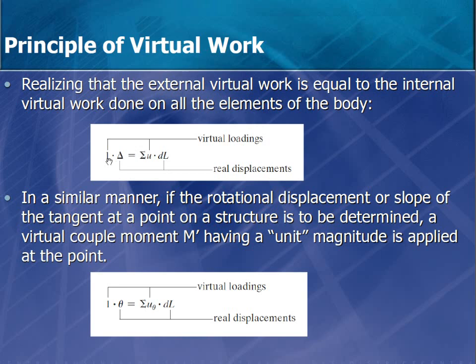Now we can say that the virtual load times the real displacement is equal to the virtual internal forces multiplied by the real displacement.